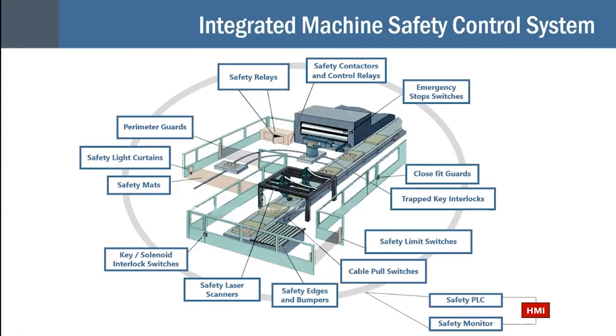That's a pretty good indication it's not wired properly as an element of a safety control system. Or the light curtain's wired to the E-stop circuit, and the maintenance guy that installed it is going to tell you that. Any of these should have their own dedicated circuit.